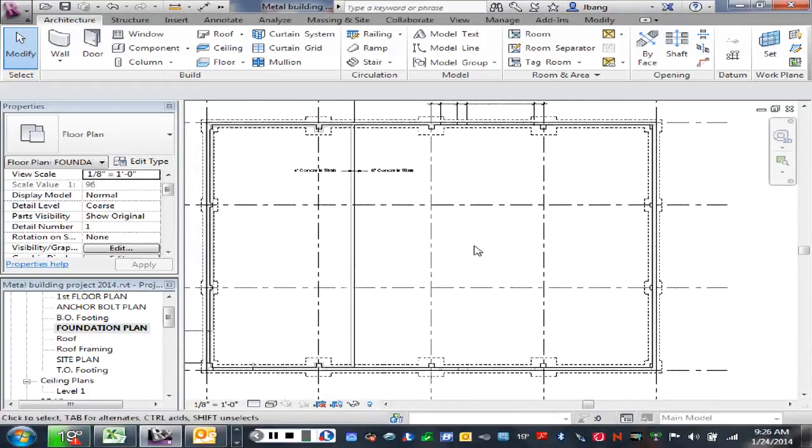So in this case, I'm going to click on this slab that I put in here. Before I do that, I'm going to decide where I'm going to put the floor drain. So in my case here, I have a door here and a door here. So you want to put the floor drain under where a vehicle would sit in the building. It's a trench drain. Let's say you bring a truck in and it's going to sit in the shop over this floor drain, and anything that drips off of or falls off of the truck ends up in the floor drain. So we're going to put it directly under the path of where a vehicle would drive into the building.